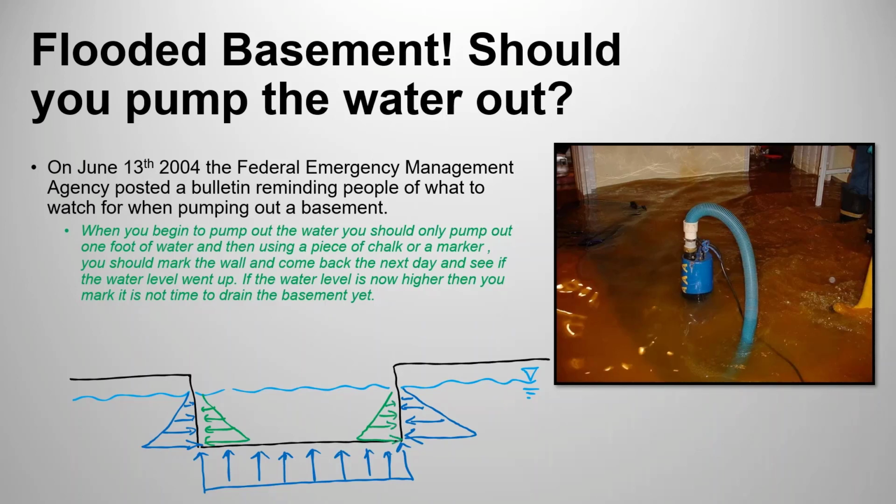If you start to pump out this water, what will happen? Think about it. If you pump out this water, there won't be any water over here. I'm just going to get rid of all these drawings. There won't be any water over here. So this resultant force and this resultant force are going to exert a lot of pressure on the walls of your basement. If these walls are not strong enough, they are going to simply collapse, right?